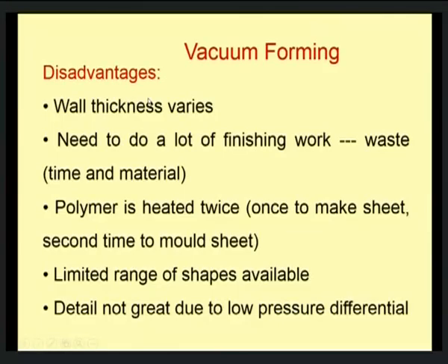Now, if you look into the drawbacks or the disadvantages, mainly the thickness of the wall. Thickness of the product would not be uniform throughout the product, therefore, this is a major issue, and also finishing work is required, it has to be trimmed up. So, that will again result in wastage of time as well as material, and the polymer is heated twice, that is common with respect to thermoforming.